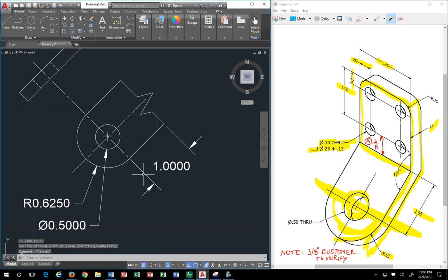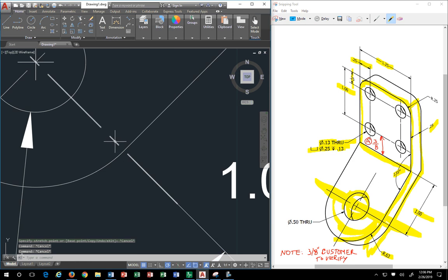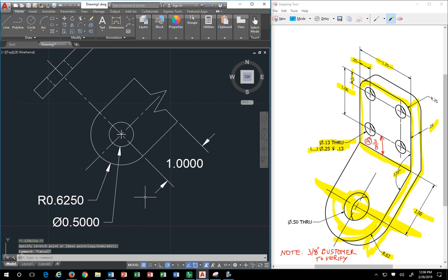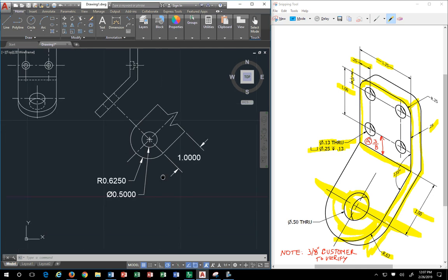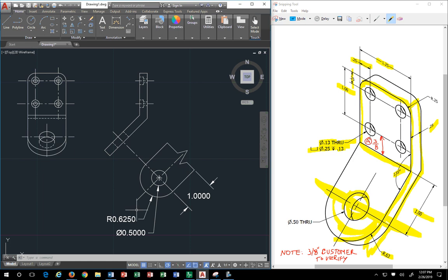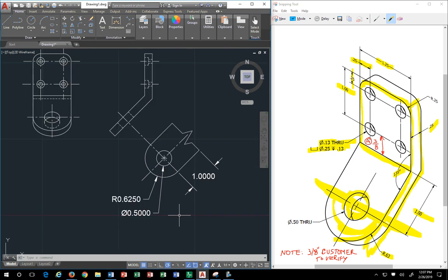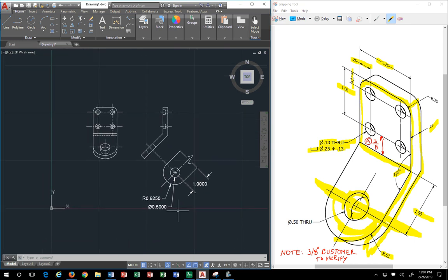between the dimension and the object. Here, the gap is there, but the center line overlaps the dimension, so I pulled it back just so that it doesn't, because I want that gap. Because you never want your dimensions to be touching the object. So for drawing the views, this is correct. Dimensioning those, another conversation, because those dimensions are way too large.